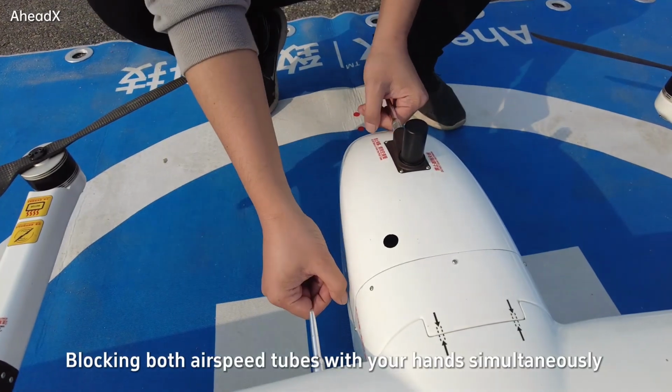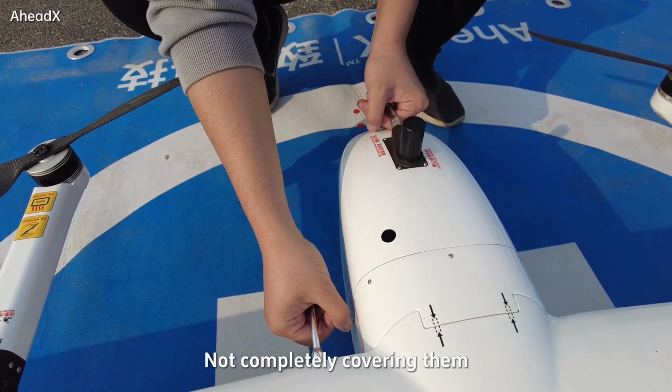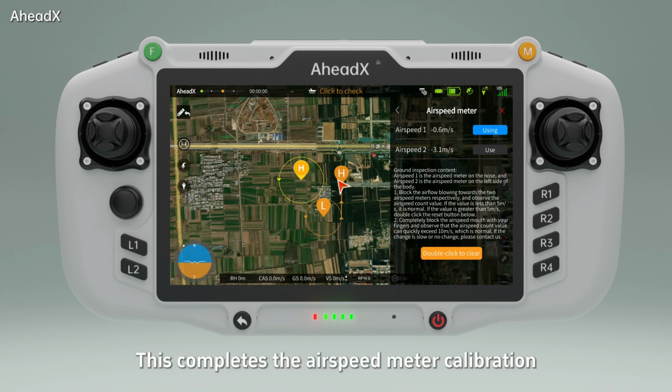Block both airspeed tubes with your hands simultaneously, not completely covering them. Double-click the button on the page. This completes the airspeed meter calibration. Before takeoff, check the airspeed meter again.